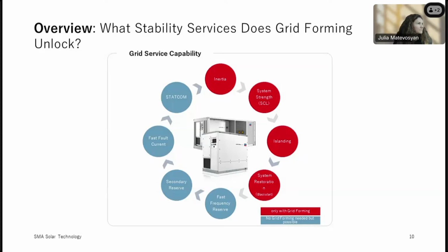Next one. Can you share some typical requirements for black start capabilities in grid forming battery storage? You want to take? Yeah, a typical requirement would be, for example, you have a gas plant which you need to black start. So it's not that your battery storage plant is the black start for the grid, but it's the black start for the auxiliary power of a gas peaker plant, for example. So all these pumps and auxiliary supply of